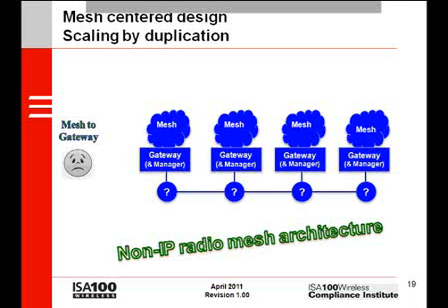Each mesh is attached to a device called a gateway. The diagram shows that each gateway device also hosts a management function. In this configuration, each gateway has a radio, and no backbone is involved in each little wireless network. Each network stops at the gateway. At the gateway, the data is translated into something completely different, such as Modbus or OPC. The connections on the other side of the gateway are shown as a series of question marks, suggesting that the high-side interface isn't specified by the standard and could be just about anything.